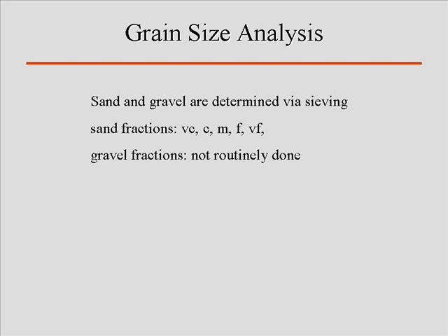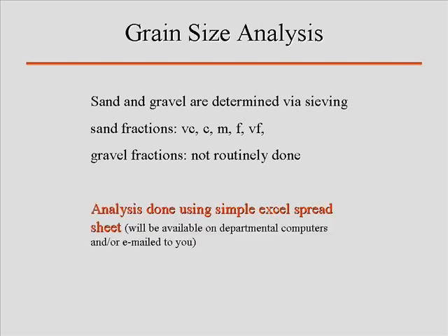You do the analysis, extract the different components from it, and I have a spreadsheet that will automatically do it for you. And then, of course, the last thing you have to do is figure out what the grain size of this is, and that's got to be done separately. You've got to sieve out the material and put it through a sieving process as well.